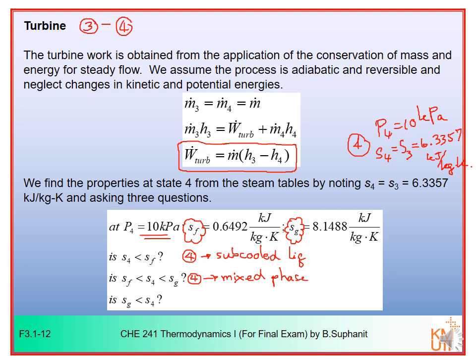And lastly, if S4 is greater than SG, it means that point number 4 would be in the superheated vapor region. Now you can see from the number that we have, S4 is 6.3357. It lies between SF and SG. So it means that point number 4 is in the mixed phase region.